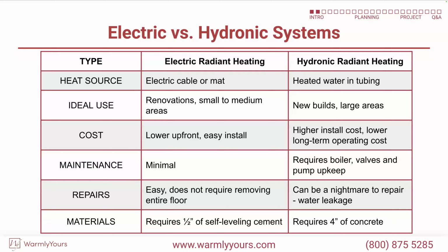And what it does is when it's laid out in the room, often when you have these tubes entering the room, they all enter in the same place and they all exit the same place. Well, the spot where the water comes in is always going to be much hotter than the spot where the water exits the room. The temperature on an electric heating cable at the very beginning is the exact same temperature as it is at the very end. Hot water, it's very hot at the beginning and cool at the end.